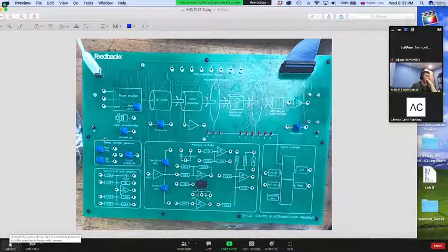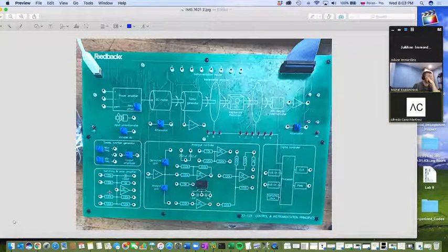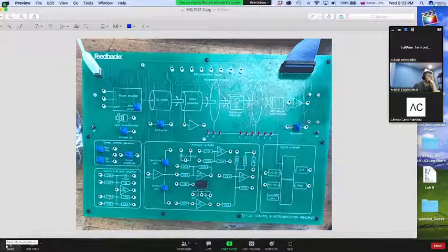So if you want the system to behave that way, you need some kind of measurement to indicate how far apart these are. This measurement comes from the error. In your feedback system, if you want to minimize the error, you need a signal that is proportional to this error so that you know exactly how far away you are from the desired position or goal or signal.